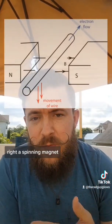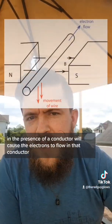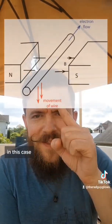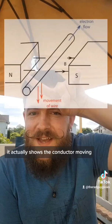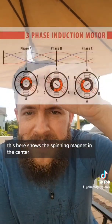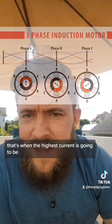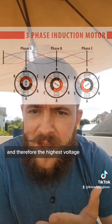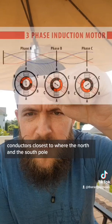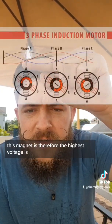A spinning magnet, or a magnet moving in the presence of a conductor, will cause the electrons to flow in that conductor. In this case, it actually shows the conductor moving and the magnet staying the same, but it's the same principle. This here shows the spinning magnet in the center. And when the magnet is closest to the conductor, that's when the highest current is going to be, and therefore the highest voltage. Here you can see the black coil conductor is closest to where the north and the south pole of this magnet is, therefore the highest voltage is.